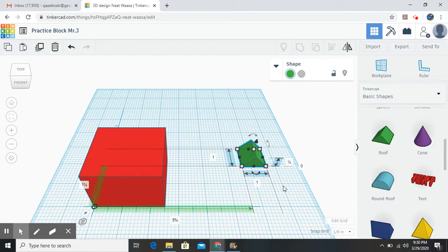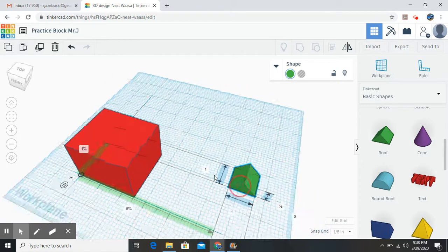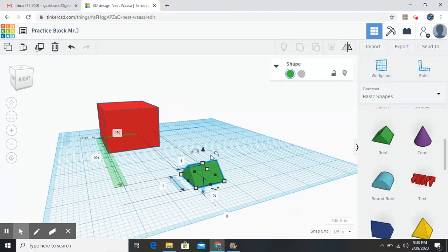So the first thing we're going to do is stand this up. We're going to click on here. You can see how it projects this axis around here. And when we do, I'm going to go up here and type in 90 degrees.